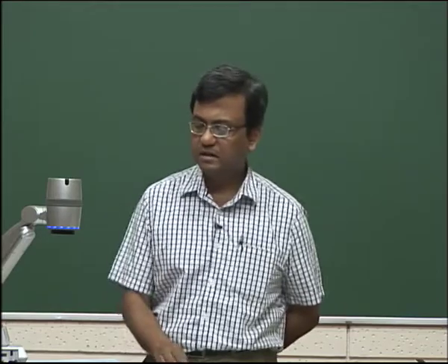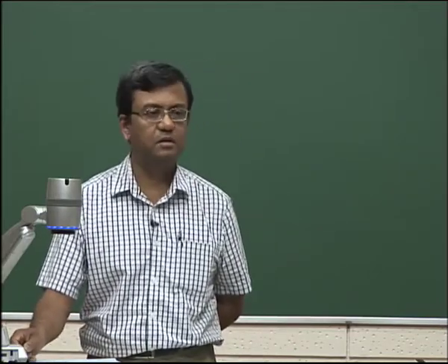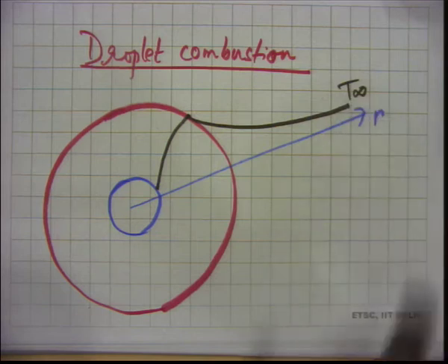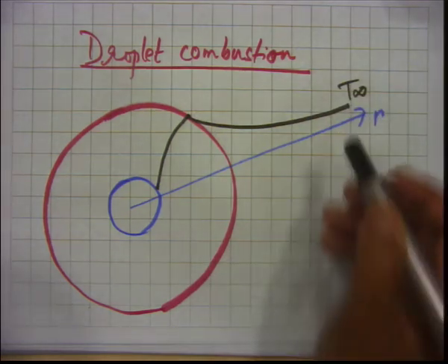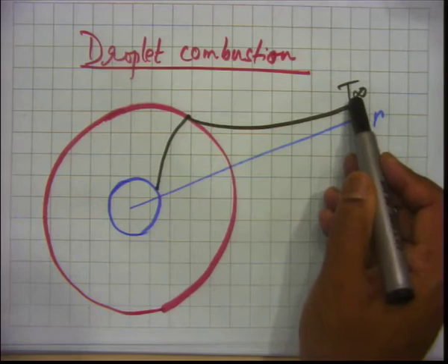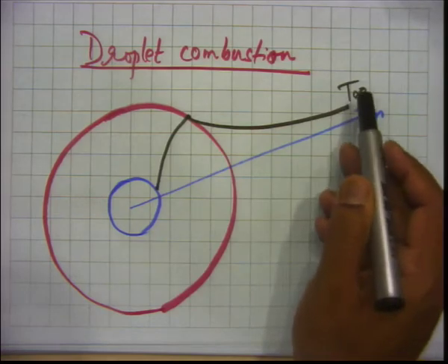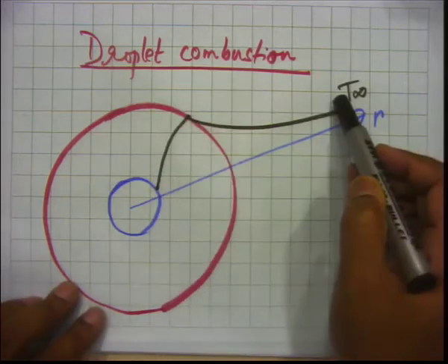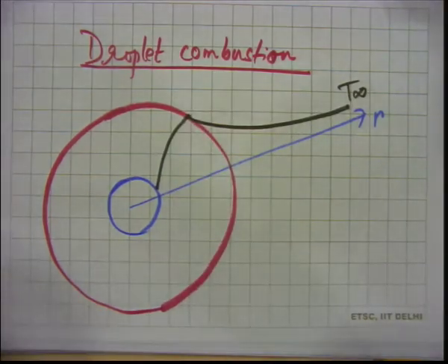So in that case, the T infinity which you see in this particular curve that I have drawn can be the room temperature also. So you have given a spark and produced a flame. Once you have got the flame, then you can get this sort of a profile. This is thin. And we can also bring in our understanding of the infinite reaction rate situation and think about what will happen to the fuel mass fraction profile and the oxidizer mass fraction profile.